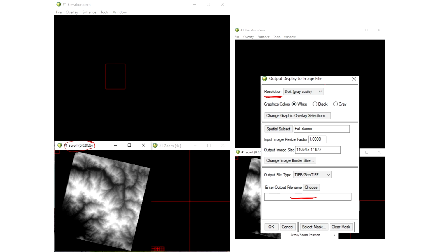So you can choose this option, and you simply choose the GeoTIFF format from this drop down menu, assign the output directory, and save your DEM. With this window you are able to save your DEM, and this DEM would be a high resolution DEM with a spatial resolution of 2.5 meters in the case of Cartosat-1 data.